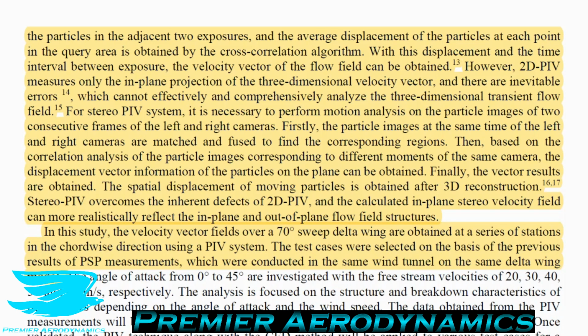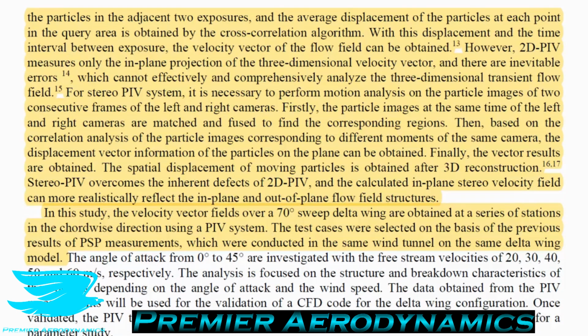So by using stereo PIV, you can then get this third dimension, and you can decouple them. So you don't only have two velocities, and both of those velocities are somewhat erroneous because the third velocity is in those two velocities just due to a parallax error and the different errors of the angles that you're looking at the images from. But also now with the stereo, you do get that third component. You've decoupled all three, and that error is not in there anymore, in any of them. If you do it properly, that is. I have to throw that specifier out because even though we do take it for granted, it's not something that we should be taking for granted because it sometimes does happen.